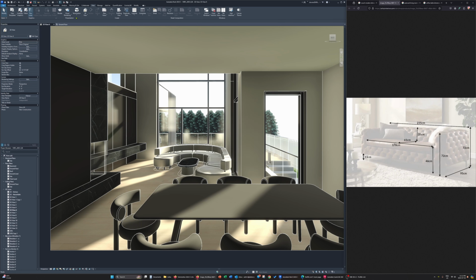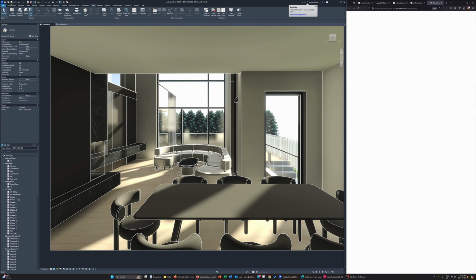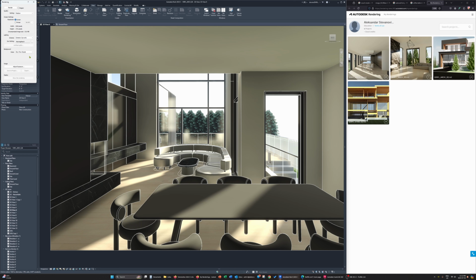Bunch of things missing, it's okay. And hopefully we're going to be able to see what this looks like. In the meanwhile, maybe I can try rendering this in my window just as a quick basis. I don't like to use this because it's going to go insanely crazy on my screen. Interior sun only, morning, March, no clouds. We'll adjust the exposure, but potentially we could use this as well.